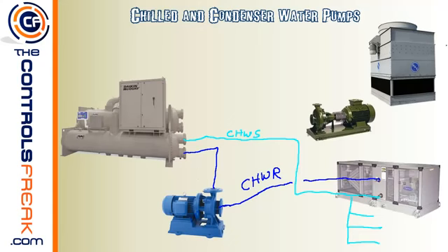On the condenser water side, you'll have the hot water coming out of the chiller. And we're going to draw this one as if it's coming into the pump. And it's going to come out of the pump and come into the top of the tower right here. So that hot water is going to come across, get cooled down with the fan on, back into the basin, and from the basin it's going to get sucked back out and come back into the chiller right there.